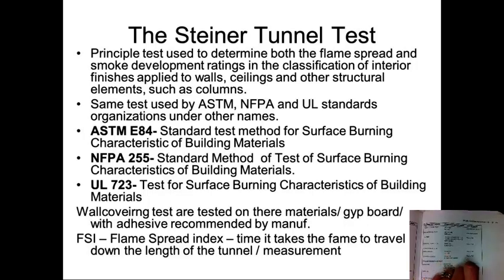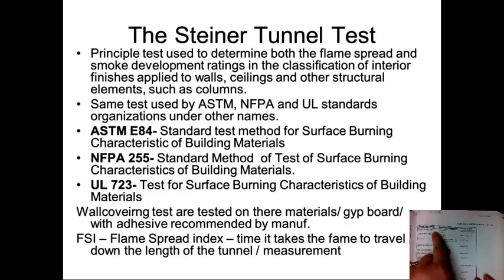A lot of times you're going to see the acronym FSI. That means Flame Spread Index. It is the time it takes the flame to travel down the length of the tunnel, and it's measured. Okay, so if it passes this, it's going to be, of course, either a class A, B, or C rating.